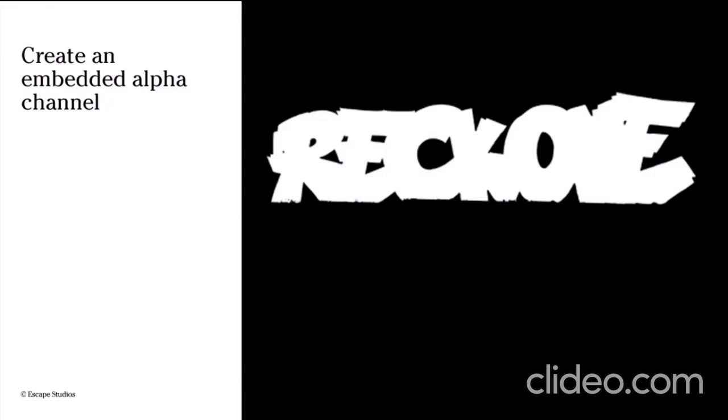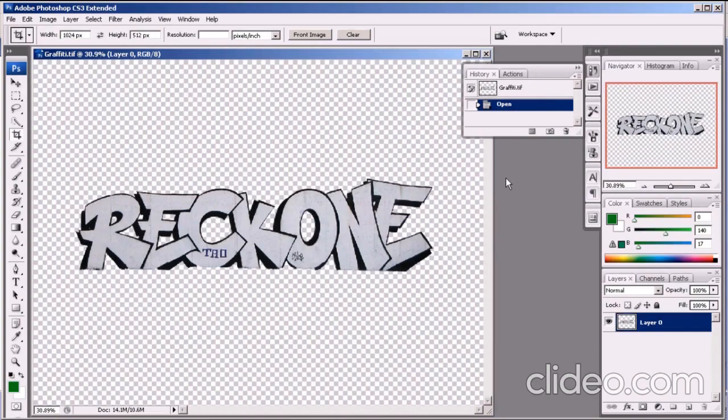Next, we're going to clean up our graffiti, resize it, reposition it, and create an alpha channel for it. So I'm going to start off by resizing my image and also repositioning where the graffiti lies in my image, and to do that I'm going to use the crop tool. Just going to clear the settings. What I'm going to do is make sure that I crop the size to a 2:1 aspect ratio, so we're going to match the polygonal planes that we made in Maya, so therefore when we apply it to the wall we know exactly where it's going to lie.